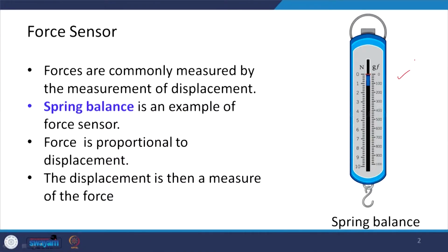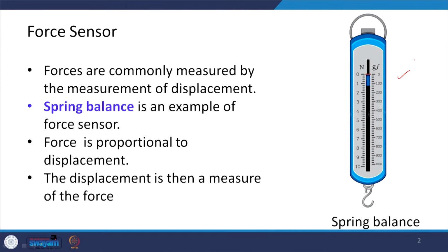A very commonly used force sensor is the spring balance, which you often see available in the market as well as in many of our houses. Now, how does the spring balance measure the force? Basically, in the case of a spring balance, the force is proportional to the displacement. So, here we essentially measure the displacement which is calibrated in terms of the force.